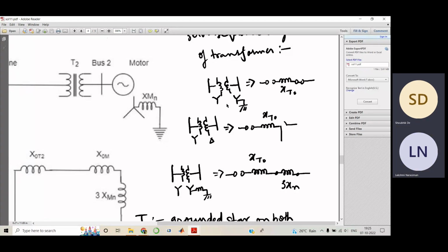In that convention case also, let's consider I am having a very big system on the right hand side, but still I will not have a zero sequence current flow into the system at all, because if I'm shorting the left side or right side, the current is going to be always zero, because I'm not having the continuity of zero sequence current. So yes, your impedance would be infinite. Yeah, that I agree. So you are trying to say how does it affect, right?